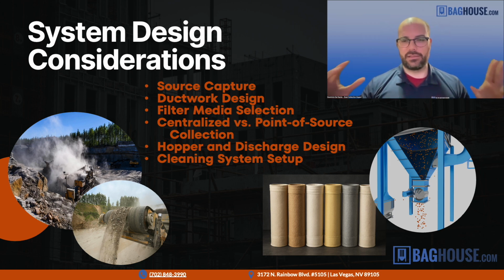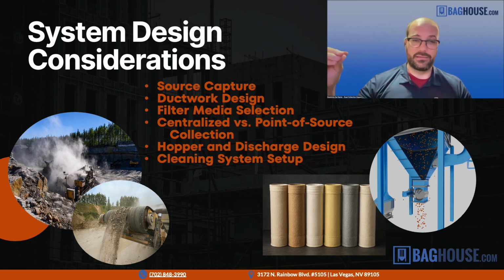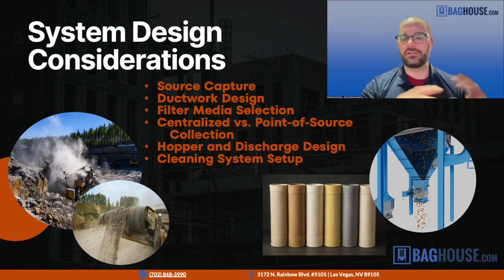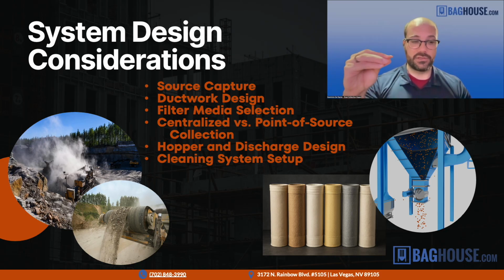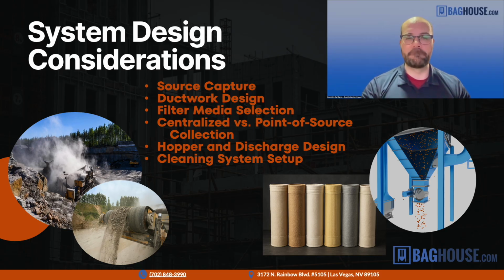The same dust collector that has 1,000 filter bags that can handle your dryer, if you try to vent a single room, can only handle perhaps a room that's 20 by 20 and only pick up light dust. Whereas if it's with hoods and ducting going right to the source, that same dust collector can handle dozens of pickup points throughout your plant. So we almost exclusively need to do dust collection at each source where it's generated.